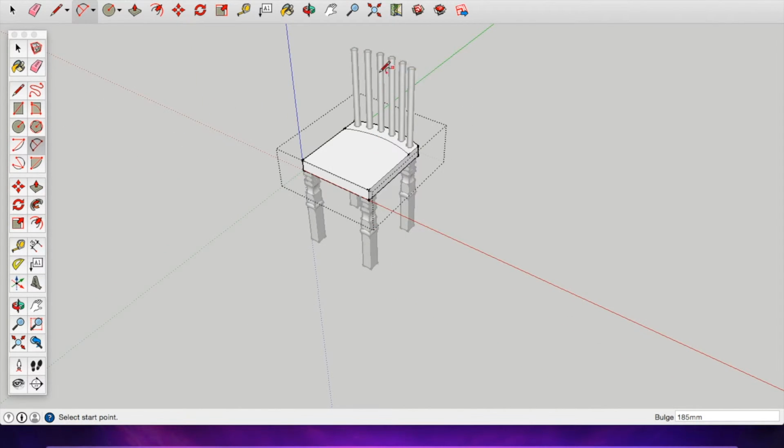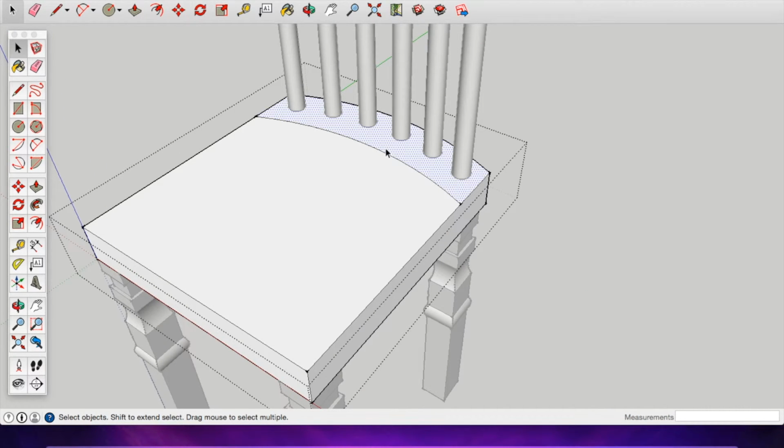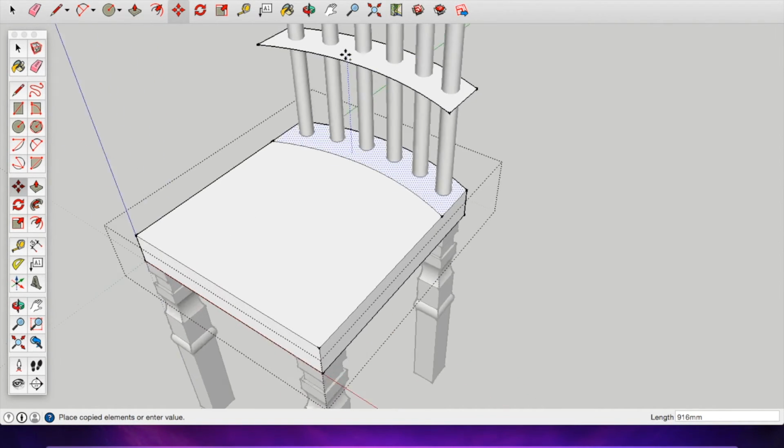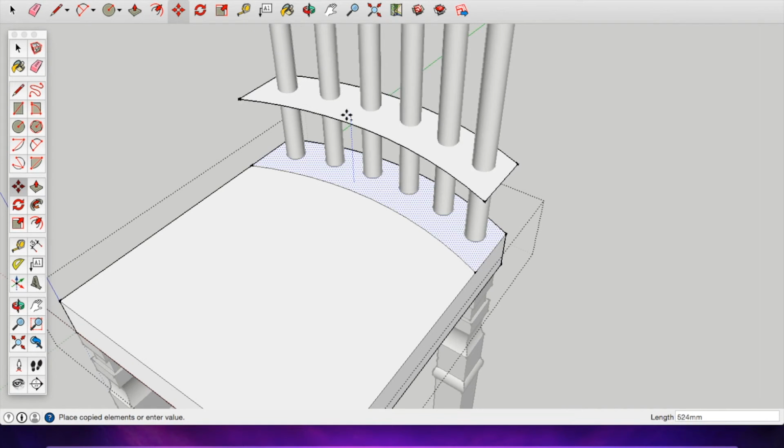It's going to end up here. Okay, I'm going to use the Select tool, and I'm going to click in the middle of that, so that's shaded just like this. Okay. Then I'm going to use the Move tool, and I'm going to click in the middle of this shape, and then hopefully I can move it around the screen. As you can see, whoa, that's going to be a little crazy, right? So I need to tap on the Option key to make a copy of that. Okay. And then I'm trying to move straight up. Do you see how mine snapped on the blue axis? If yours does not do that, tap on your up arrow one time on your keyboard, and then try to move it around, and then it should lock into place.